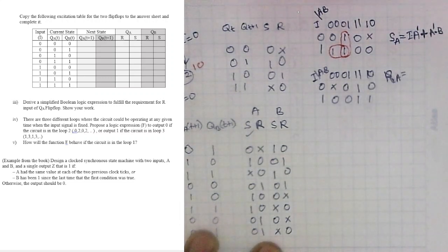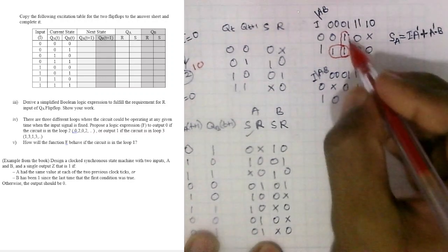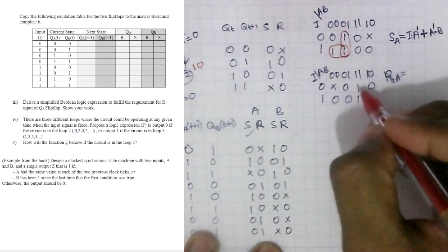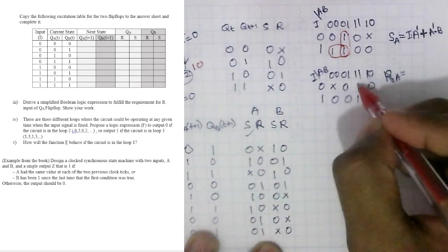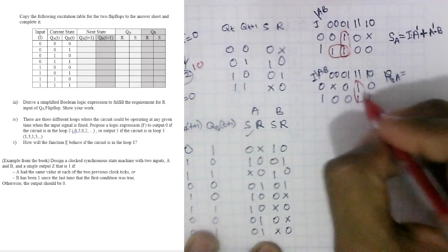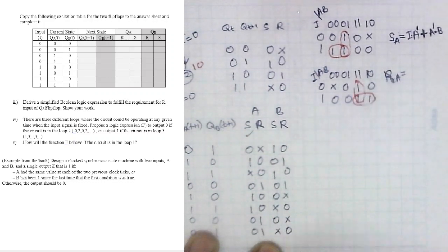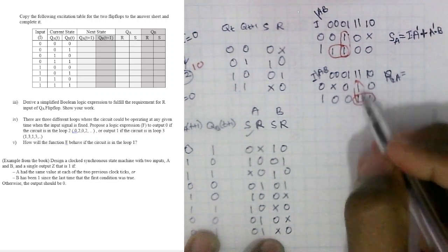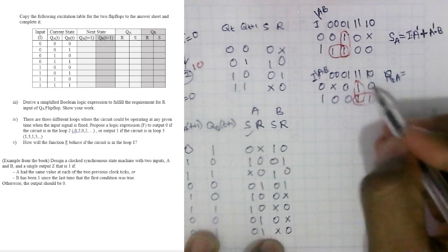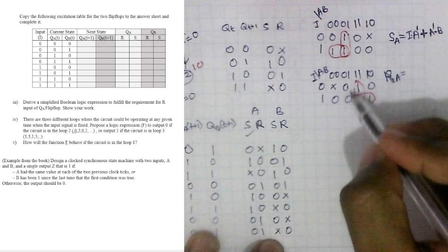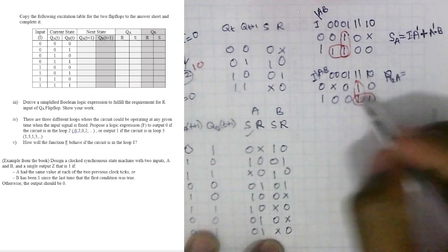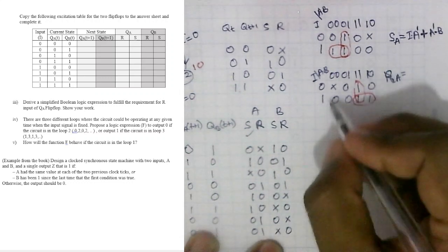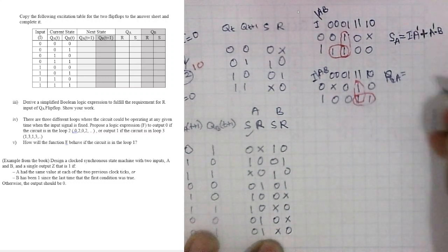Okay, so now what are the groups? Again, it's essentially similar, but we don't need to include this one. You can go with this group and this group, right? Because this one does not contribute to any of the bigger groups. If there was an X here, then it would be quite easy, you could bundle everything together as a single group, but here it is a 1, so it is no use for us.